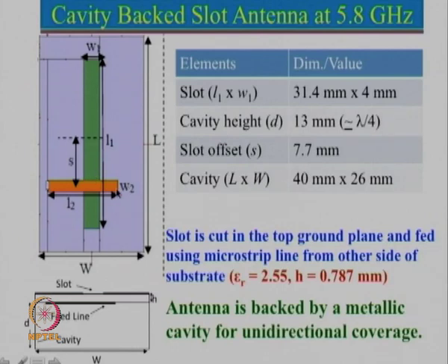So, just to tell you here, current is 0 here and current will keep on increasing. At a distance of lambda by 4, current will be maximum, and at a maximum current there will be a magnetic field which will be maximum, and that will get coupled to this particular slot here. So, if we choose lambda by 4 length here, that will give rise to maximum coupling, but we can control the coupling from here to this slot here. And why do we need to control the coupling? Because we would like to have impedance matching with the 50 ohm line.